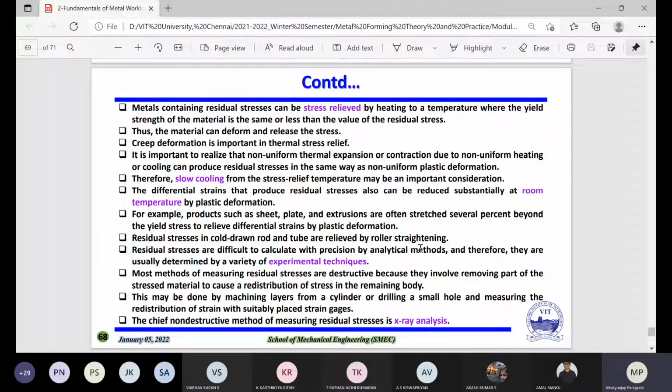But if you put another thermocouple touching the sample, or with a 1 mm gap to the sample, then that temperature will be the accurate temperature, or the actual operating temperature. So you have to add one more thermocouple. Many people are not considering that, because they think the furnace temperature is that one, so my sample is also heating at that temperature. No, this is wrong actually, right?